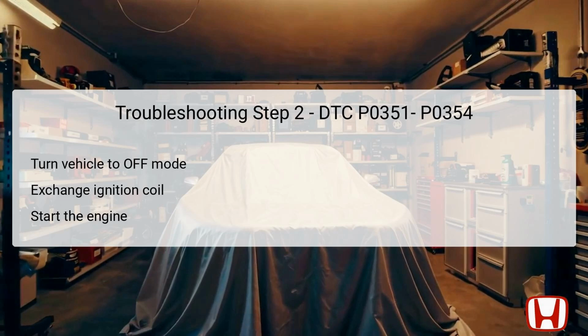For the second step, begin by turning the vehicle's ignition off to ensure safety while working with electrical components. Next, swap the ignition coil from the affected cylinder with one from another cylinder. This step is crucial in isolating the issue.